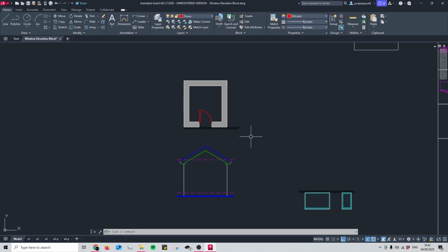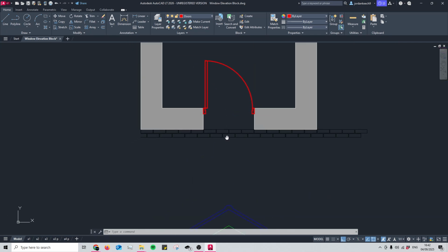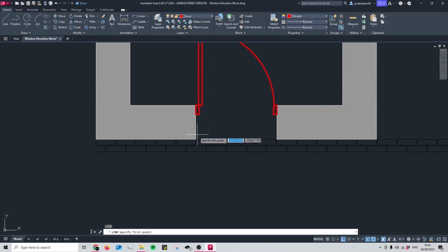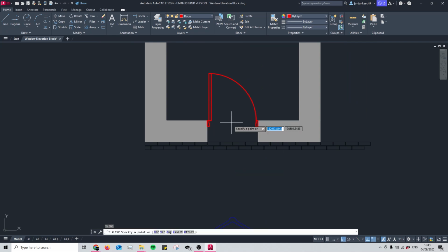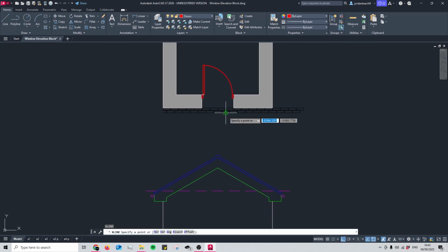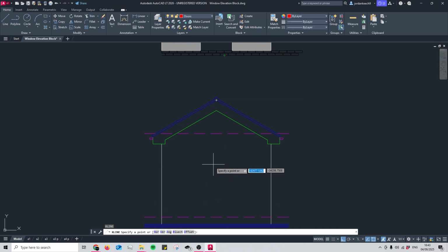So as you can see, the building lines up with the brick guide and the door fits in between the bricks too. A typical front door in the UK is around about 910mm wide, much like I have here. Using XL, which is the construction line, I'm going to define the left and right hand side of my door for our elevation.